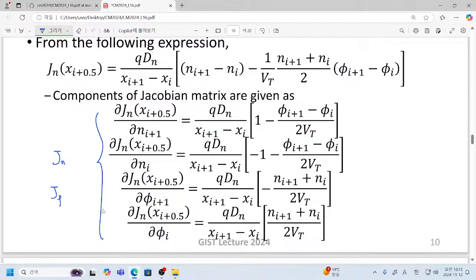First of all, please identify the root cause of your convergence problem. Root cause means that when you have the Newton-Raphson method, you always construct the Jacobian matrix and residue vector, and by solving that system you get the update. And in many cases, the update is so simple. Once you have a solution, you just subtract the update from your original solution.